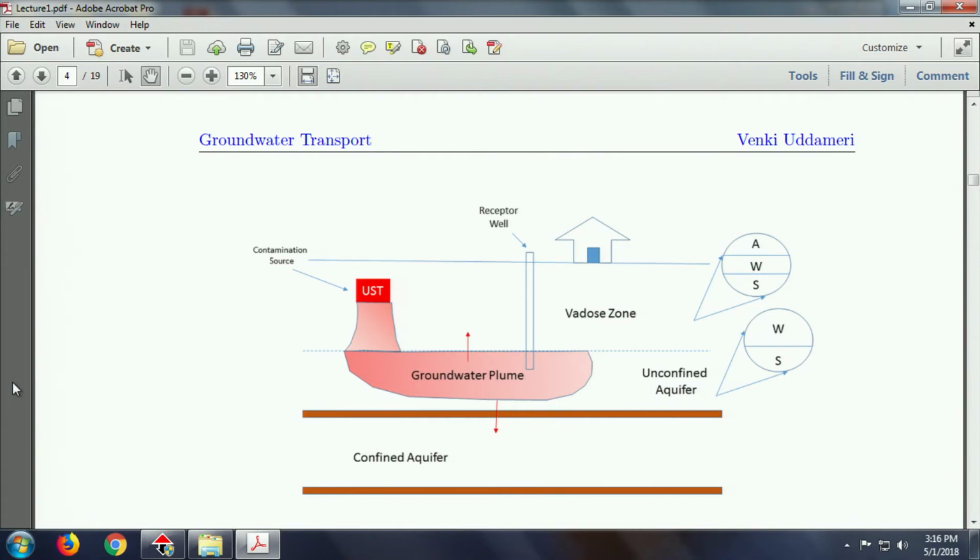is we have an aquifer, so it is not a free flowing system. You have a very tortuous path, a very heterogeneous path, so you cannot know where your flow lines are. The brute force method would be to trench out something, put a barrier here, so that as the water moves through that barrier, it will clean itself out. That's one way to do it. A more sophisticated way is to strategically put wells and then inject chemicals so that we make sure that we are cleaning it.